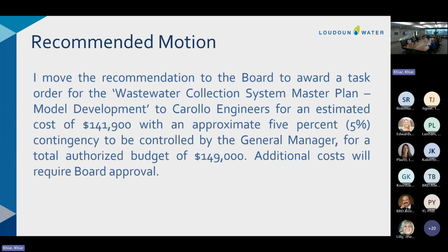Just in general, I'd say that the accuracy, or working with trying to calibrate it, is really tricky on the sewer side. Because we have, yes, those base flows, which are based on the development that's there. But then we also have the influence of rainfall, and as our system ages, will we get more leakiness into the pipes? Perhaps, but we may also get more conservation from the users, and we're trying to balance those and see how the system reacts. And as we do rehab, it continually changes the system. So it's fun.